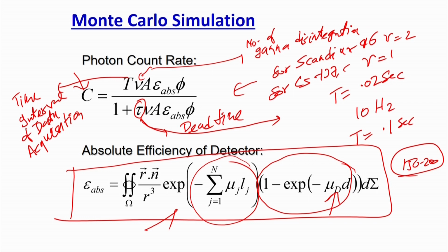This is not based on linear interpolation; at each position you are solving an equation. So, you get counts which are more reliable. You do the calibration at certain locations, tune your Monte Carlo program, and at each and every location you can calculate the count which will be recorded on a detector for a fixed position of the tracer particle.